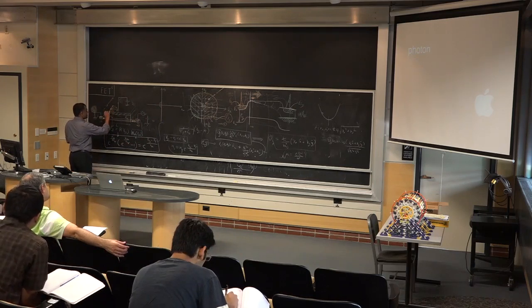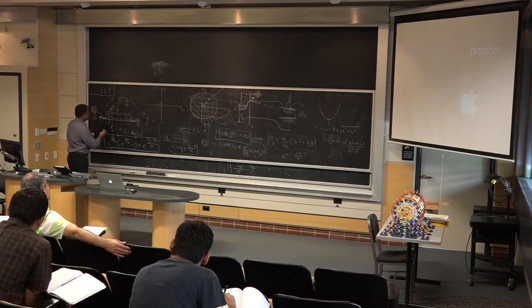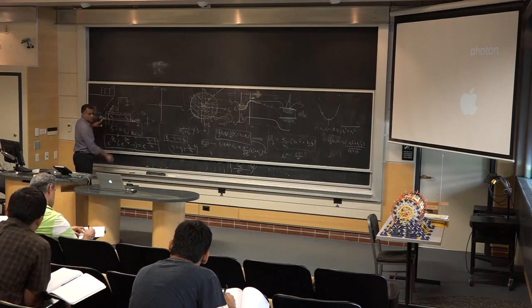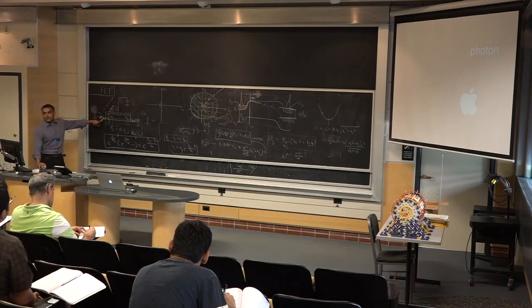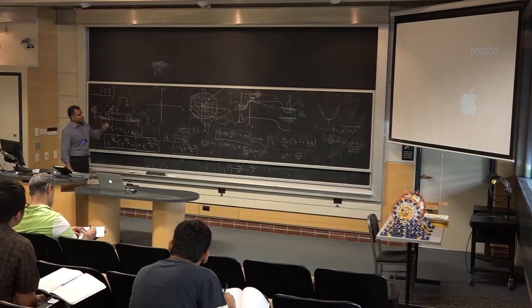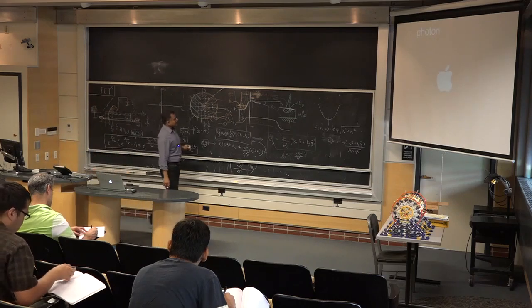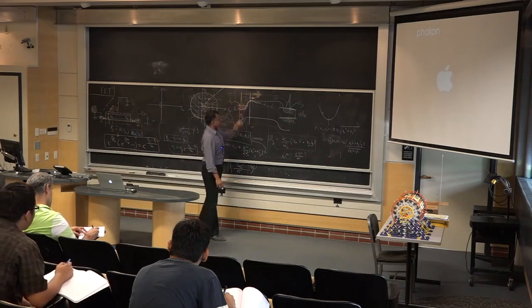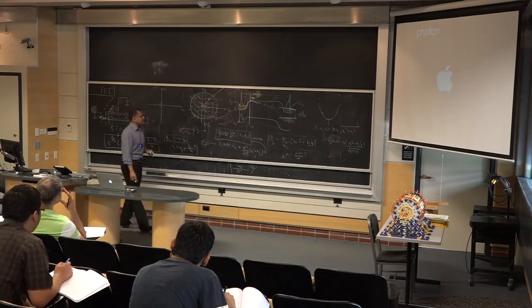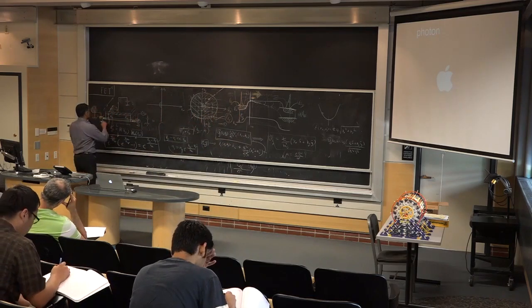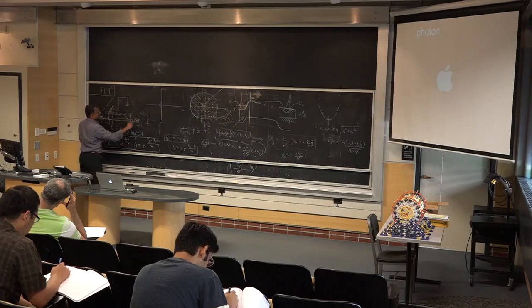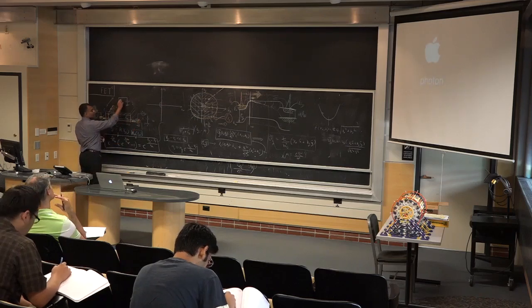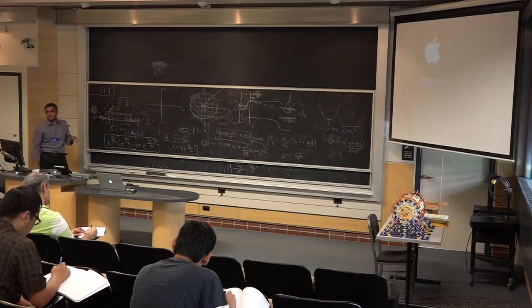In a well-designed transistor, the carrier density at the source injection point is not controlled by the source or the drain. This is the heart of a field-effect transistor. The carrier density that is responsible for most of the transport in the channel at this source injection point is controlled neither by the source nor by the drain. It's only controlled by the gate. The gate has complete control over how many carriers are there at the source injection point.